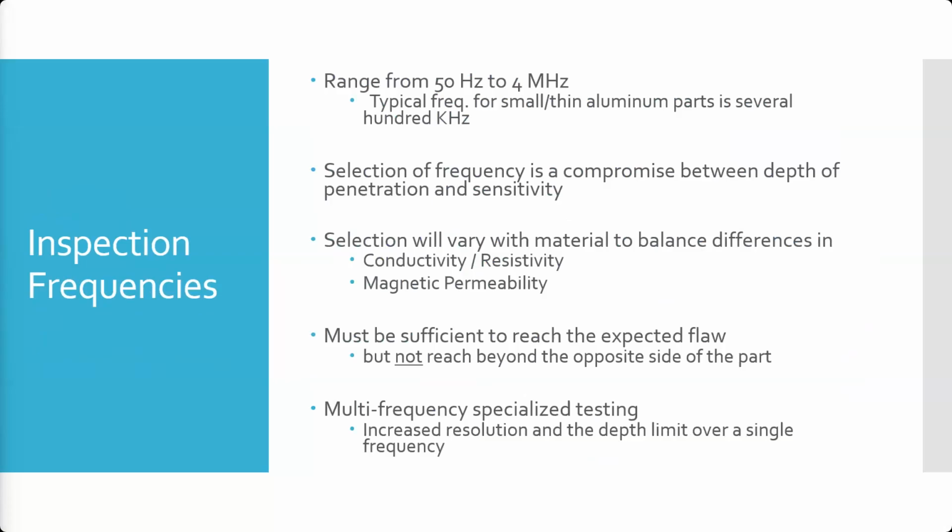They're not as common, they're much more expensive, and the testers that run them are much more expensive. But they do exist. Actually, this tester can do multi-frequency, but it can only do multi-frequency with a single coil probe. So it's not a great multi-frequency tester. They have to both be within the range of the probe size you've selected. So that gives you increased resolution and depth limit over a single frequency. Okay.